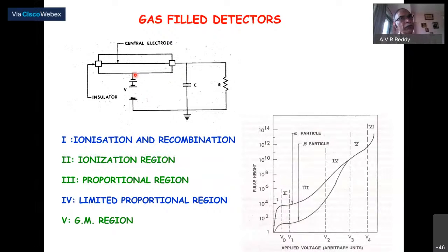Once the electric field is increasing and a charged particle is there, in fact a pair, then they get accelerated. When they get accelerated, their kinetic energy will increase, and this effect will be felt more on the electron, being a lighter particle. And therefore the moment the kinetic energy exceeds the binding energy of the electron of the molecules,